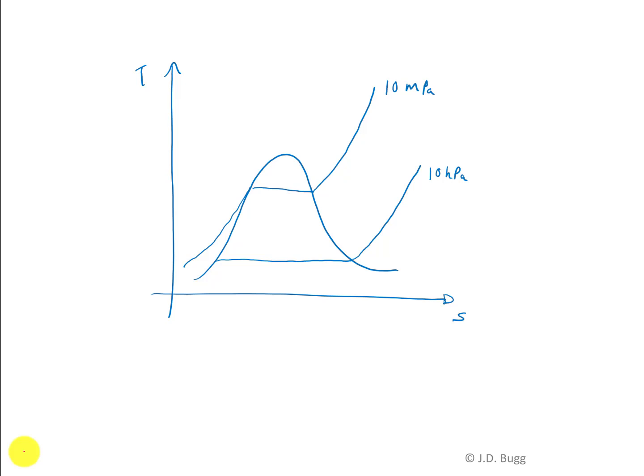Now in terms of showing the cycle on the T-s diagram, we'll start off at the inlet to the pump. So the exit of the condenser, inlet of the pump, is right here at state point 1. You can look for that numbering back on our schematic diagram. That's the inlet to the pump, saturated liquid at 10 kPa. It's an isentropic pump, so on the T-s diagram it goes straight up. So point 2 is right there, the inlet to the steam generator. The steam generator is constant pressure heat addition, so we go up there to saturated liquid, across to saturated vapor, and then up into the superheated region.